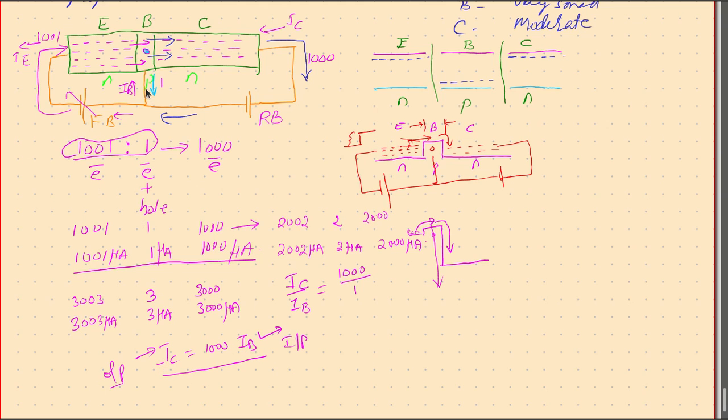So whatever is the base current, depending on this ratio, there is amplification, and this ratio is called HFE by some terminology, beta by some other terminology. Whatever the terminology used, it is the current ratio, output current to input current, and that depends on this doping ratio, and that's going to decide the 1 to 1000 ratio, and that is going to make the whole wonders begin.